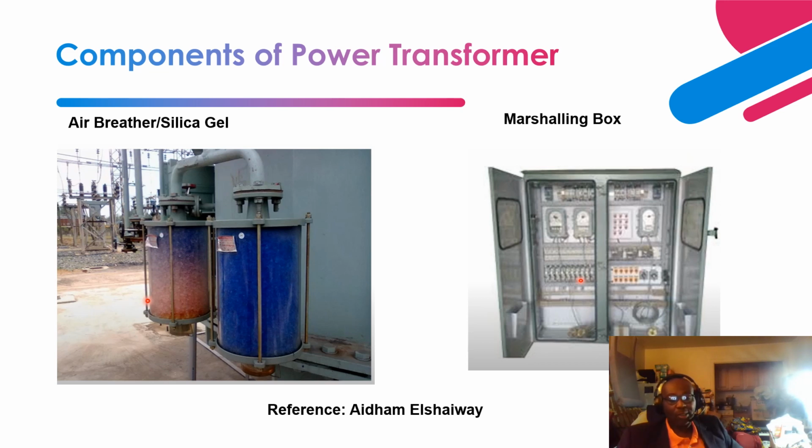It's going to deplete this silica gel and change color from blue to pink within the shortest possible time. The goal of this silica gel is for it to last between 6 months to about a year. So the pot of oil here is what regulates that amount of air intake so that the silica gel can last longer on this transformer.